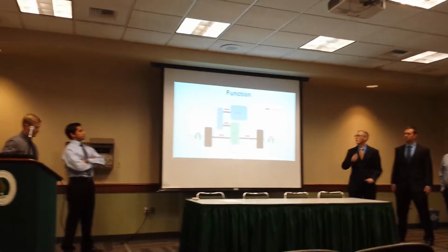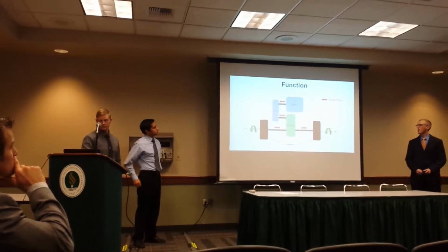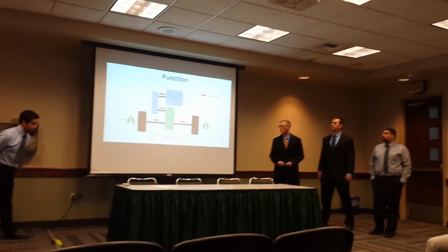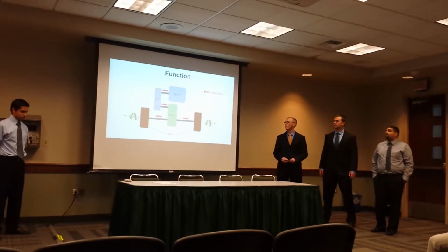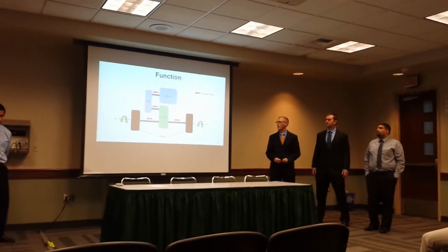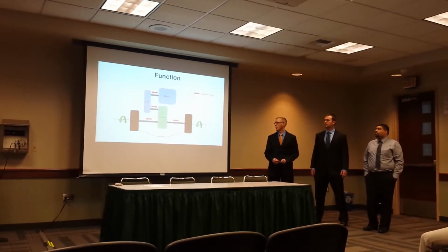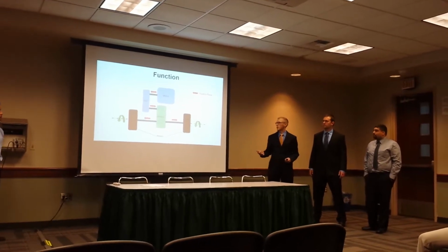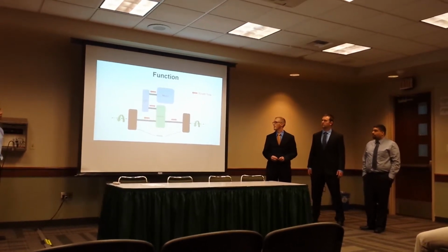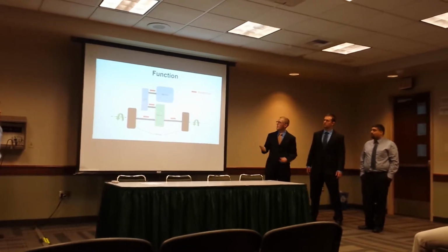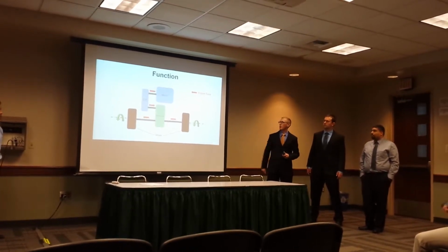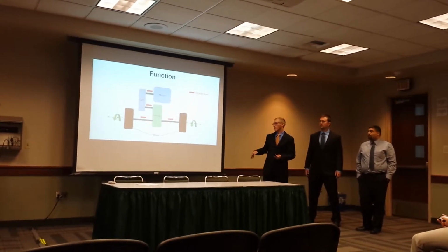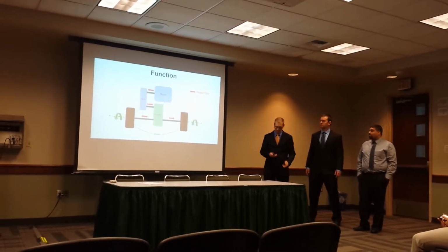All right, I'm going to talk about the function. The function of the gearbox is to be a gear reduction, which means that it will reduce the angular velocity coming from the motor, and also increase the torque to deliver the necessary torque to the drive axles. It will also serve as the power transmission. So you can see the power flow coming from the motor. It will be transmitted through the CVT, and then into the gearbox and through the gearbox and out the drive axle.